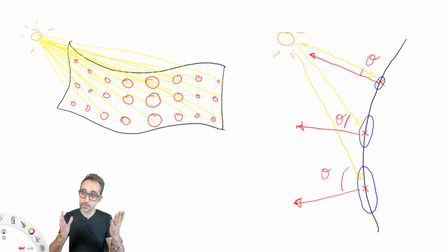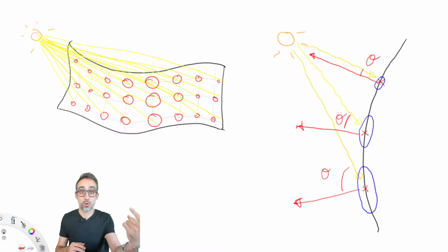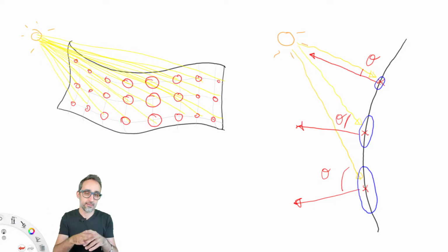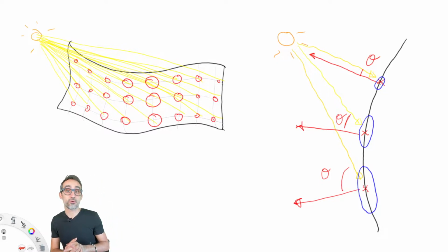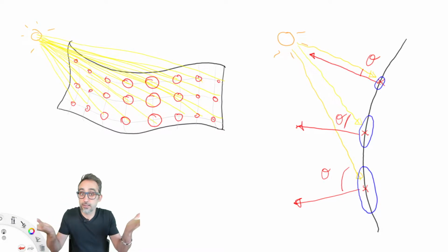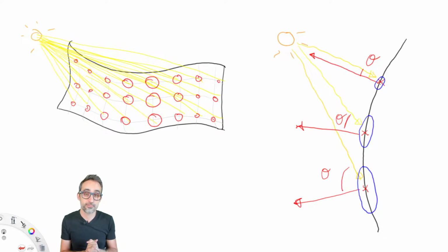We're going to subdivide the surface into a bunch of points in the UV direction. We're going to calculate the normals to the surface at each one of those points, and then calculate the angle between the sun and each one of those vectors. And then, given that value of the angle, we will design openings on that facade that will be proportional to that angle. Let's take a look at how to do that in a simple way.